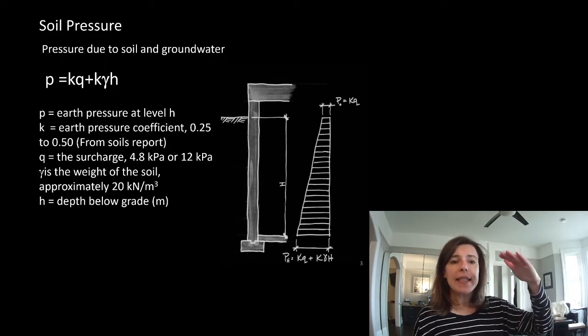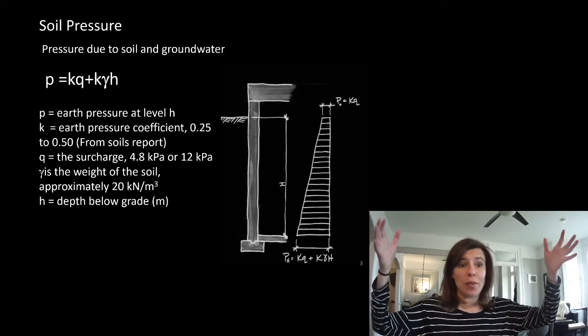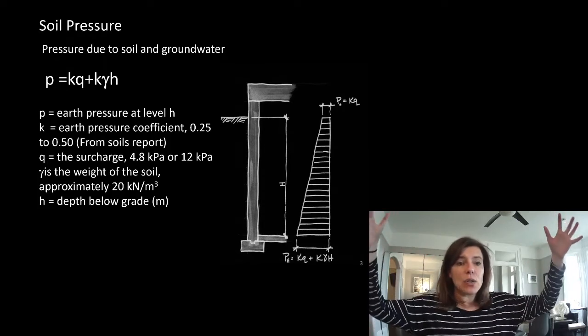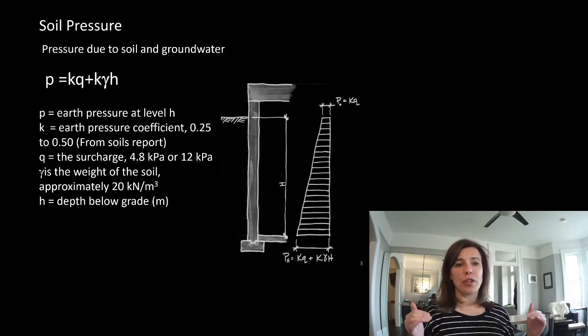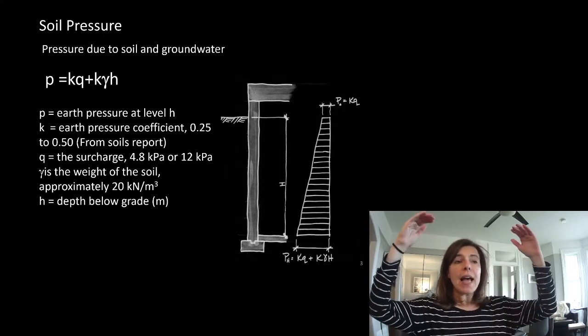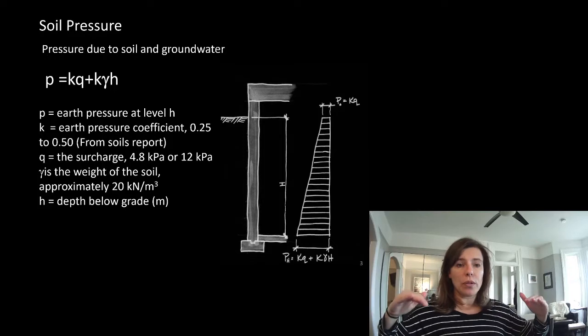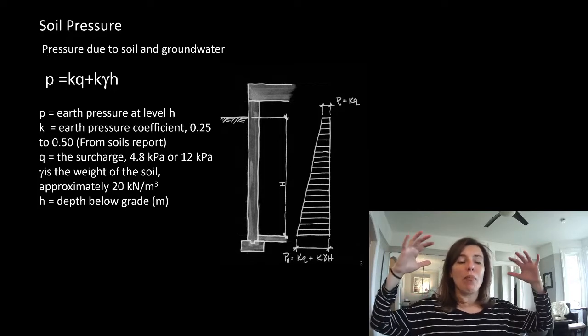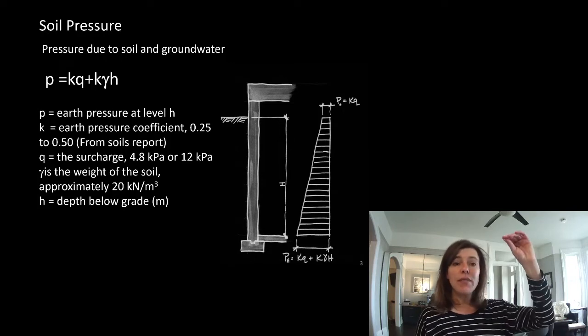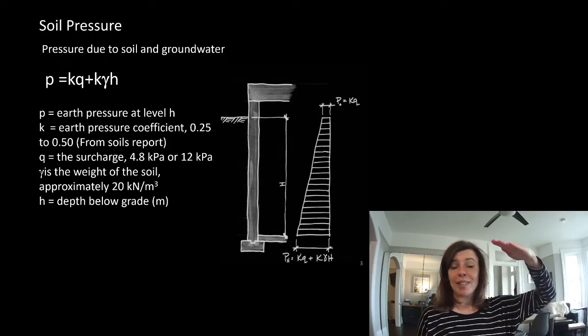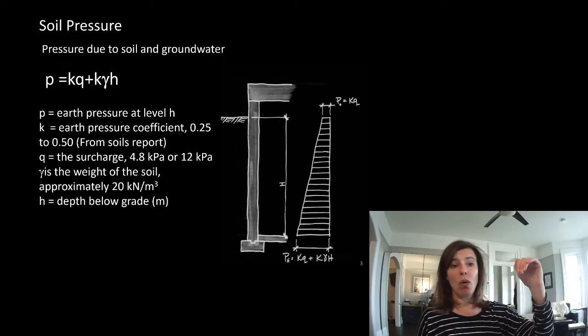As we get deeper down, you guys have seen from probably building in the sand that the soil tries to fill in the bottom first. That's because that's where the pressure is the highest. As we go down the soil, we have more weight above, and it's the weight above that's trying to make it fill in that hole. So at the very top, there's no soil above it, and it's not trying to go in the hole.